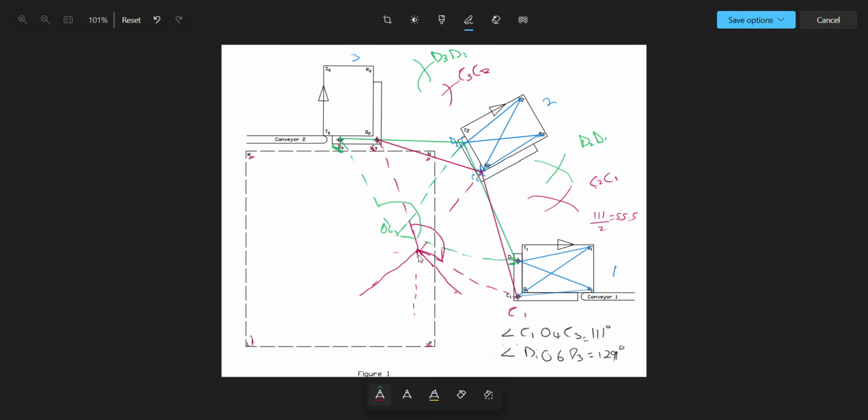Yes. So you stand at this point with your compass, you open to any arbitrary radius, and then you draw an arc. Draw an arc here, and then you draw a line to pass through the arcs. Yes. So you see, I got a horizontal line. You should get a horizontal line if this line is vertical.